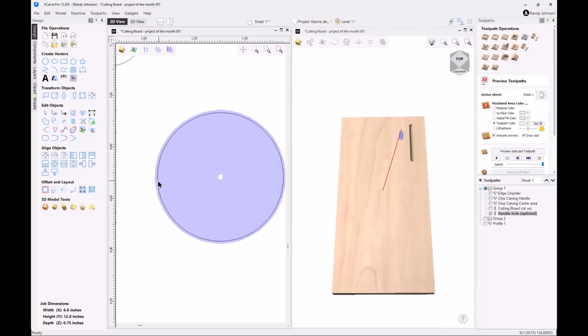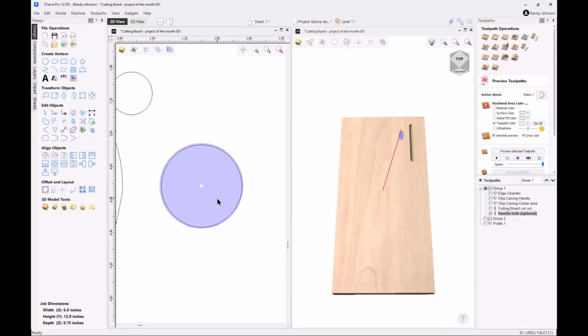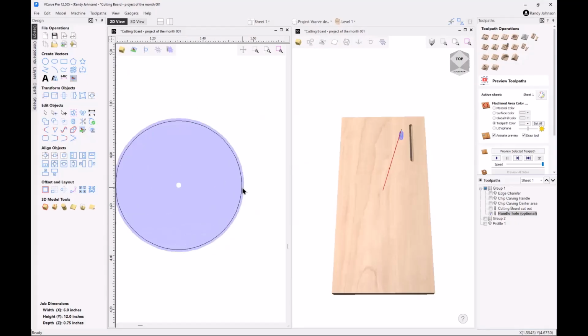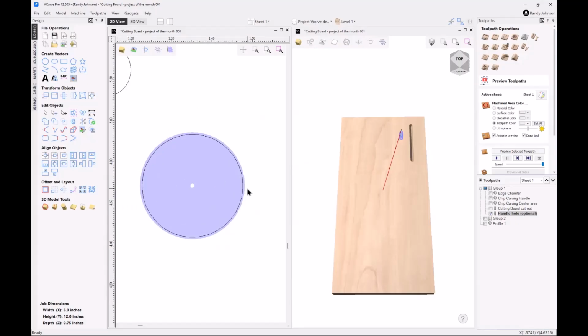Just remember that it's adding it to both sides. So if you're making your dowel and your hole, you're going to want to add the correct amount accordingly. Otherwise, it'll end up being too big or too small. So that's one way that you can make your dowels fit. And yeah, this is a great tip. I do this a lot. I teach it in my other classes. We have a project actually where they have to fit like 6 different dowels and they have to match it.